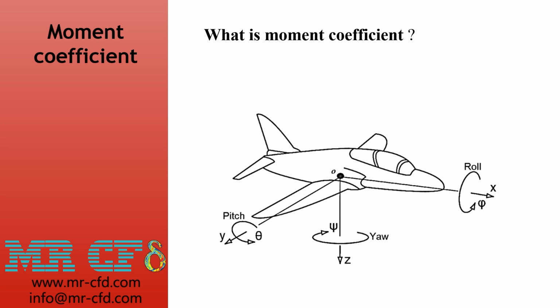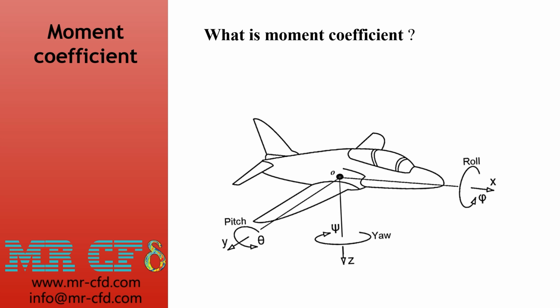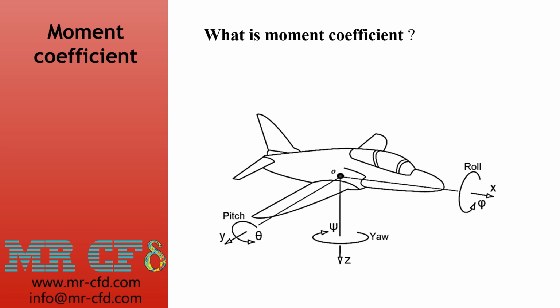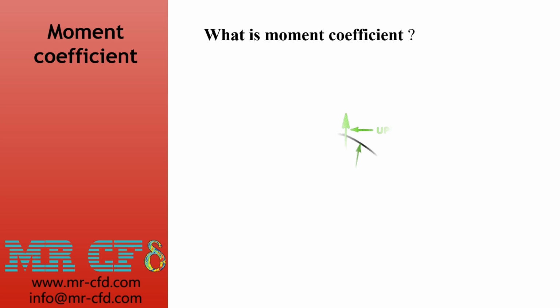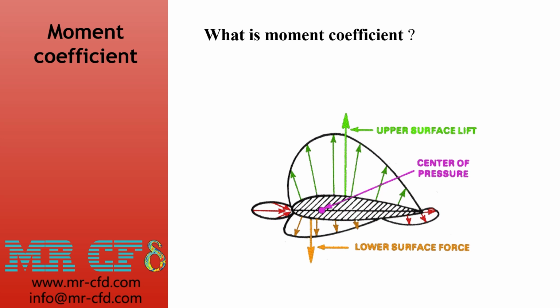However, as the angle of attack changes on a cambered airfoil, there is a movement of the center of pressure toward the aft. This makes analysis difficult when attempting to use the concept of the center of pressure. One of the remarkable properties of the cambered airfoil is that even though the center of pressure moves forward and aft, the lift can be imagined to act at a point called the aerodynamic center.